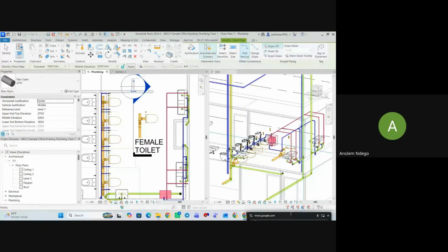If you go online to source any family, some people can create a plumbing fixture equipment that you classify as plumbing fixture, but they will create it as plumbing fittings, like pipe fittings. So when you want to generate your schedule or pick those families, you'll be lost as to where those families are.